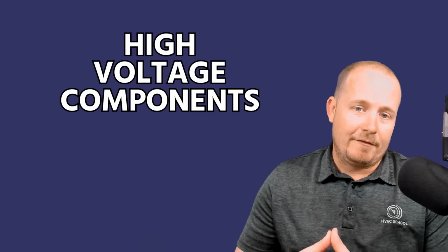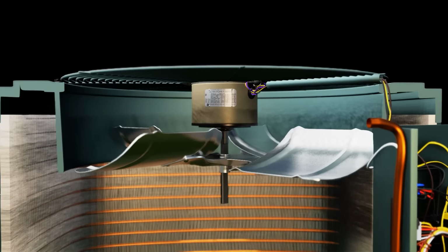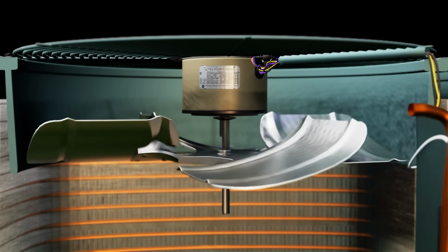And then finally, we have our high voltage components. We have our condenser fan, which is our outdoor fan. We have our blower motor, which is our indoor fan that blows air inside the space. You have your heat strips, which are those high voltage electric heaters that are used generally for backup heat. Sometimes they're primary heat in markets that don't get very cold at all, like South Florida. And then you have your compressor, which is the heart of the system.